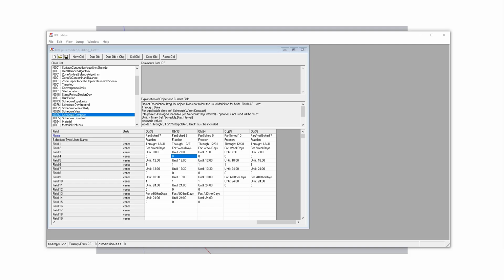It actually has a time-based variation, and you can assign different values like occupancy, lighting, or HVAC operations based on specific hours of the day. For example, you can set higher occupancy values during work hours and lower it during the off hours. And there's also an ability to choose day types.